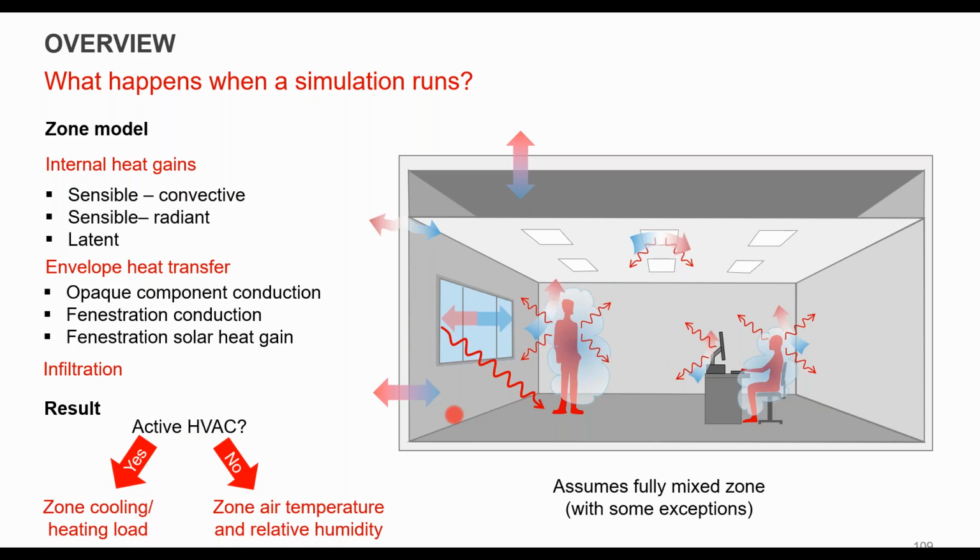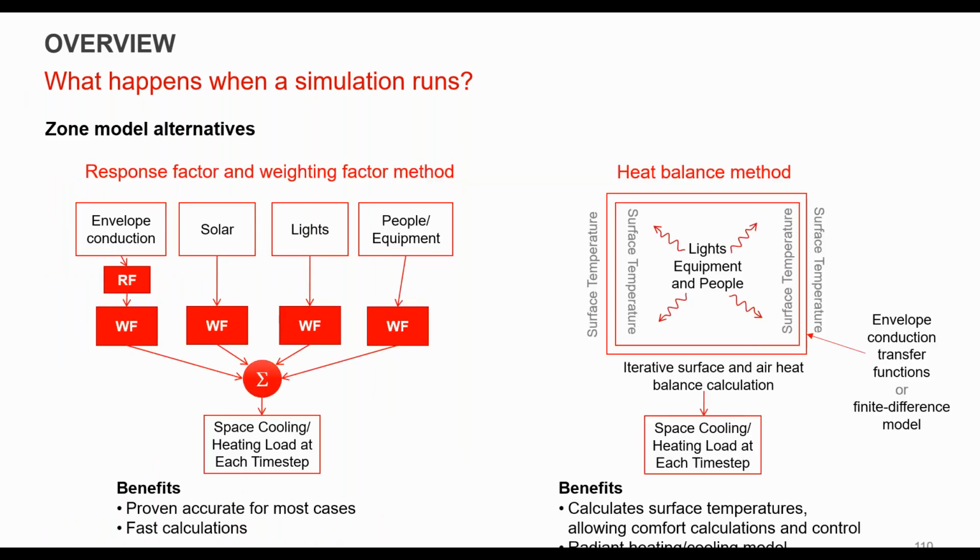Same goes for an underfloor system where you might have a colder mass of air or a hotter mass of air below the occupied level. So there's different ways, and I've seen models that have 5 or 6 different levels of stratification for very large envelopes. And some softwares will also do some interior CFD to account for heat transfer between the different stratified zones. So it's a different approach, pretty technical when you get into it, but you can basically just create zones that are stacked on top of each other to account for them.